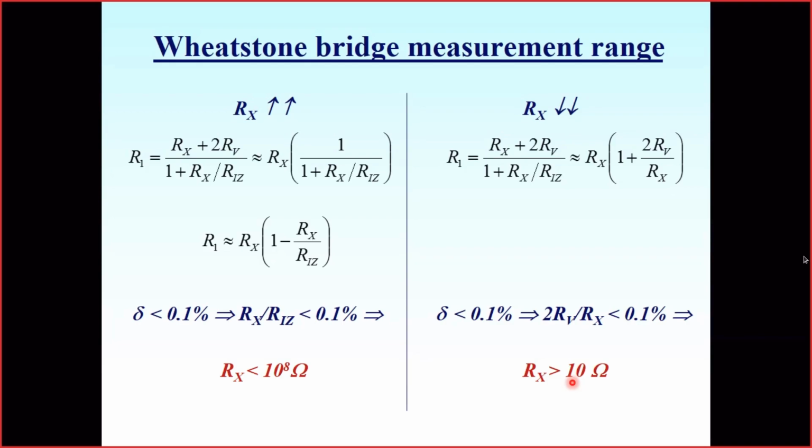So they could measure the intensity of light, including infrared light, and they are very teeny, very small, usually made of platinum, covered with a porous platinum or special porous carbon to be as black as possible. But because of their small size, they have a very small resistance. So in a measurement device, we are very often interested in measuring very small resistance.